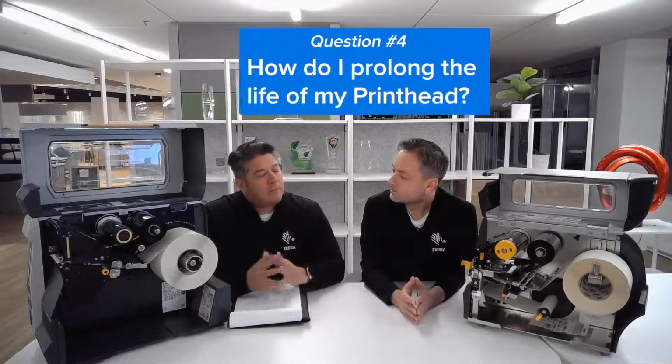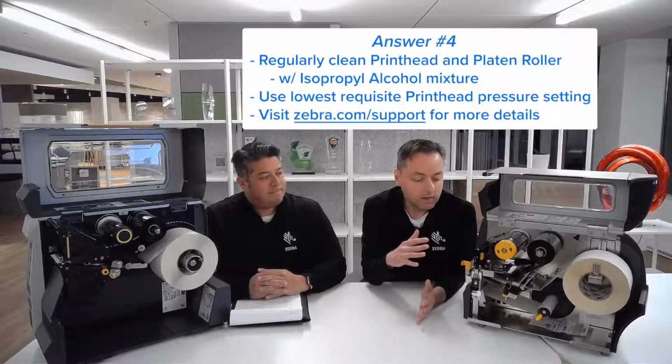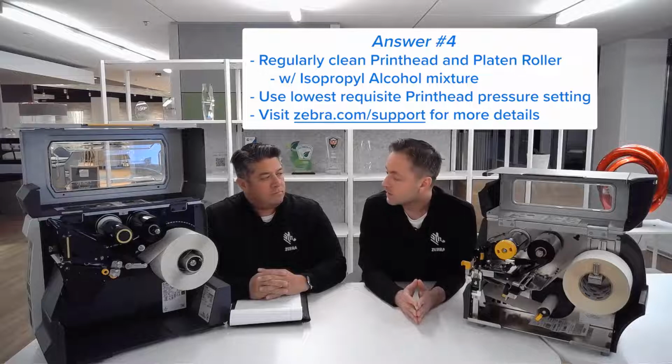Sure. Okay. So last question I get a lot is about print heads. How do I prolong the life of my print head? Yeah, so on our industrial printers, there are some parts that need to be replaced periodically, consumable parts. The print head is one of them, the platen roller is another. And just by cleaning those components periodically, you can actually extend the life of those parts several fold.